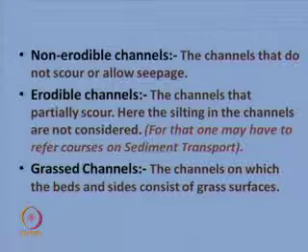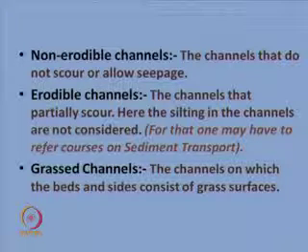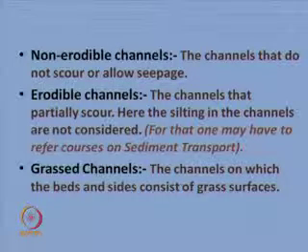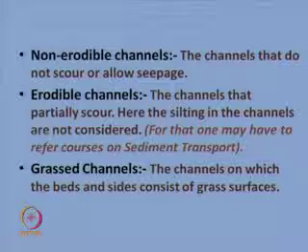So, what is meant by non-erodible channels? The channels that do not allow scour, or do not allow seepage through the bed and the sides, such channels are called non-erodible channels. Generally, you line the channel bed as well as the sides with certain materials, so as to avoid these properties.